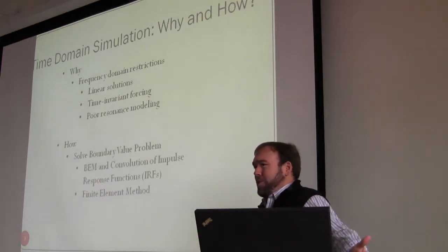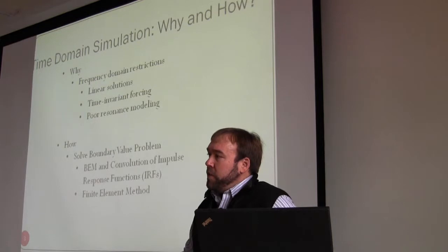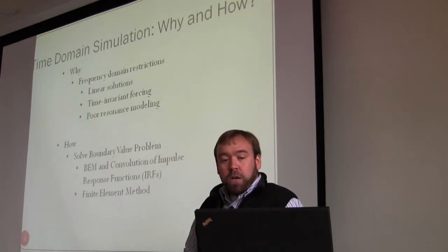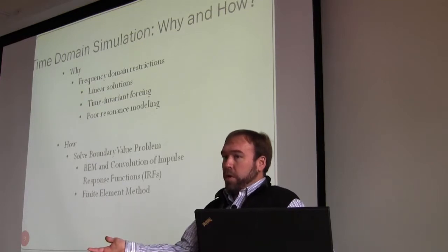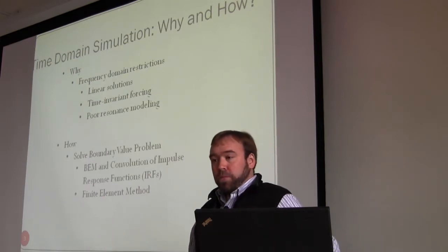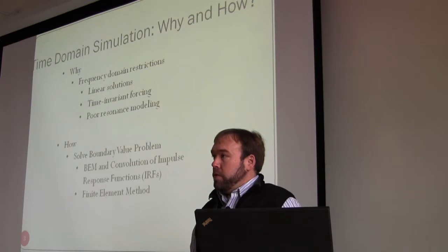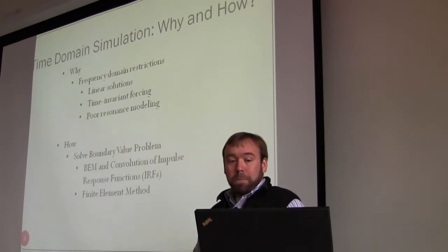So first of all, time domain simulation. Again, I think we all know this. There's a lot of limitations when you use a frequency domain. Everything has to be linearized, time invariant, obviously, by definition. And specifically when we're considering wave energy converters, there's usually poor performance around resonance. And that's due to the fact that you have small perturbations around the free surface and small amplitude motions.